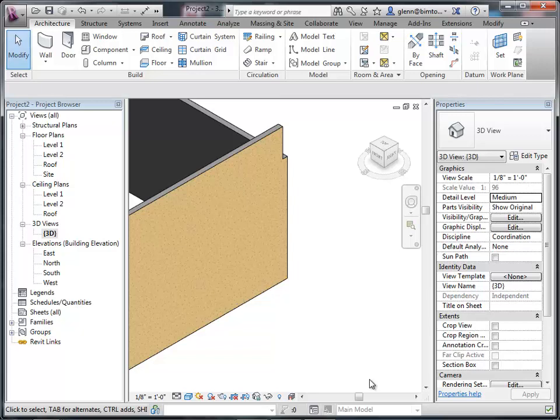Yes? So right now, is it actually assuming you have 5.5 inches of solid wood? Yes. Can you model studs? Actually, you can. It's kind of a real mucky thing. We'll probably do it on Wednesday. Usually what I would do is actually fill it with insulation and then model the studs as separate elements that go inside the insulation. Okay, it's a little strange. Those rhythmic structures of alternating materials are hard in this game. But we're going to hit it with rafters and joists too. So it's all the same sort of issue.